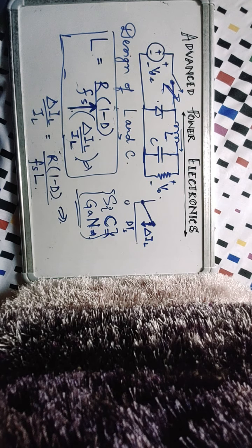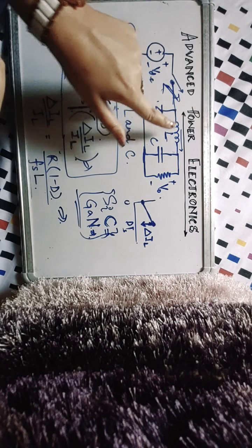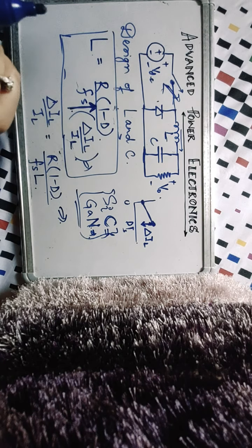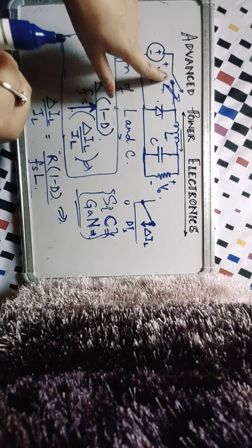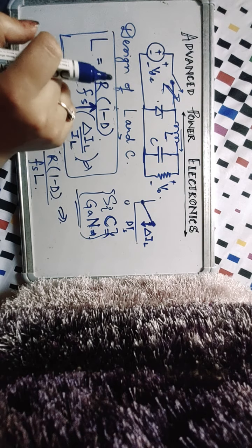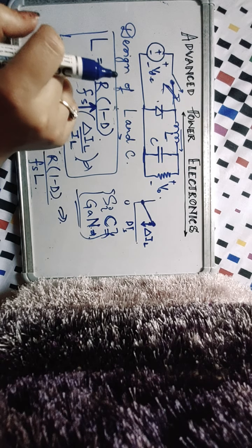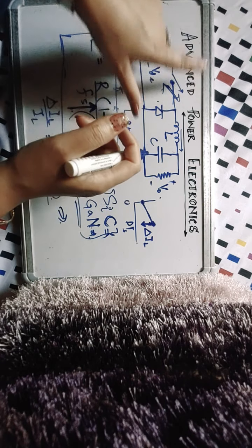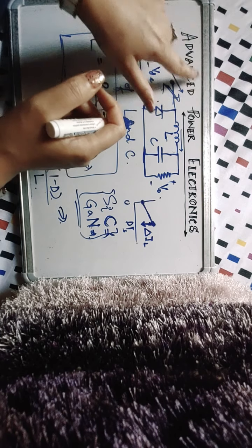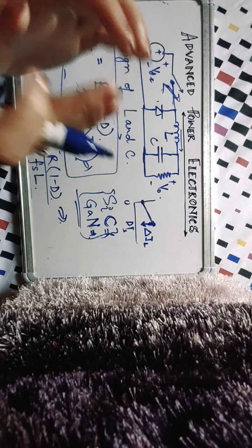You have to strike a very fine balance: your switching frequency should be high enough that L and C are very small, but it should not be so high that your device burns off, or that you may need a very big heat sink to protect the device, but then the heat sink will increase the size. So it has to be a trade-off.